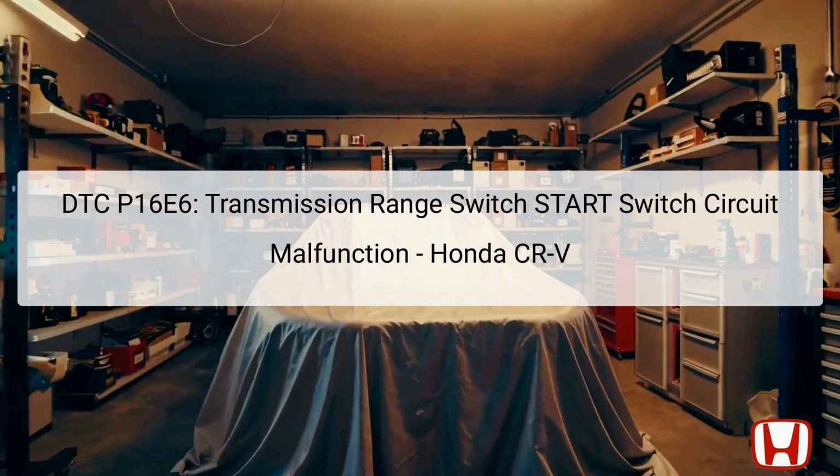The transmission range switch is crucial as it determines the current gear of the vehicle and allows the engine to start when in the correct gears, namely park, P, or neutral, N. It is typically found on the transmission assembly, making it a component that is directly tied to vehicle operation. Diagnosing this code involves detailed steps, including utilizing specialized diagnostic tools such as the Honda Diagnostic System, HDS, to clear DTCs and measure continuity. Understanding the context and components related to this trouble code is vital for accurate repairs.